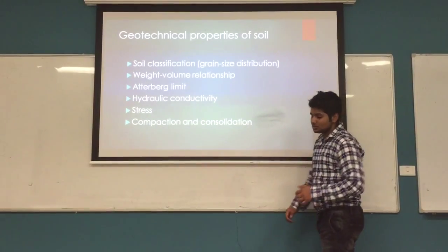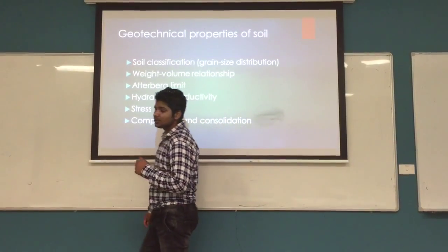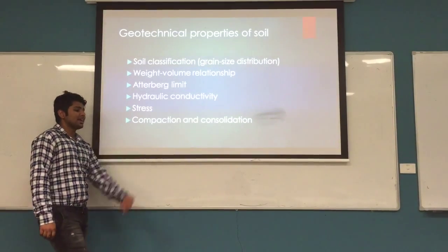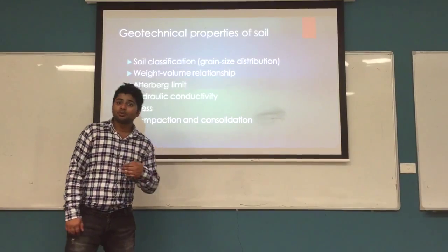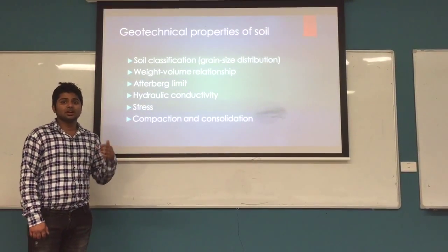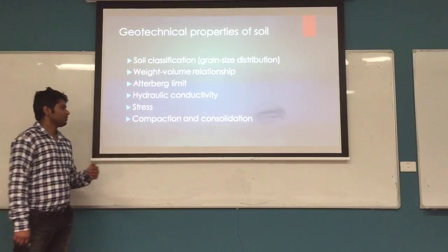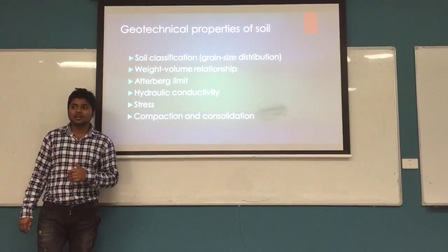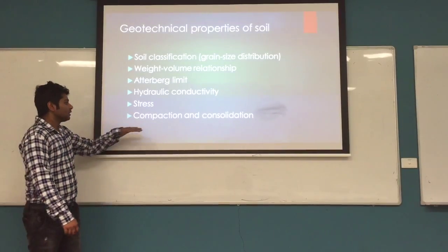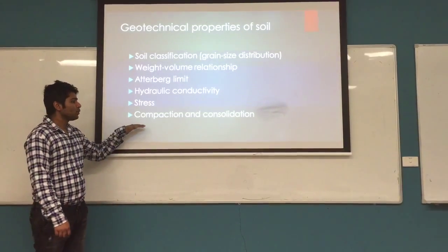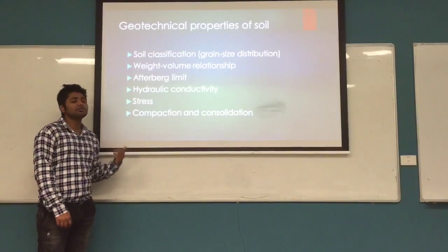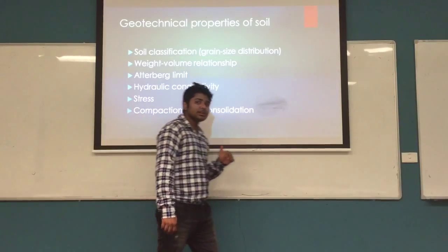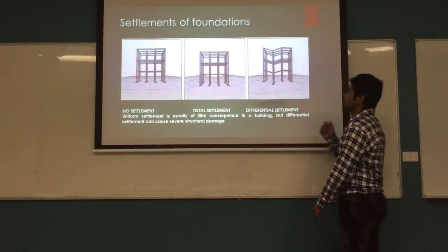And stress can be defined as the sum of the effective stress and the pore water pressure. The stress helps to determine the property of the soil to resist the load from the structure. Compaction and consolidation. The degree of compaction and consolidation are also to be determined, as these factors play a significant role in the settlement, or they may give deflection for the foundation. That's why the degree of compaction and consolidation are also to be determined.